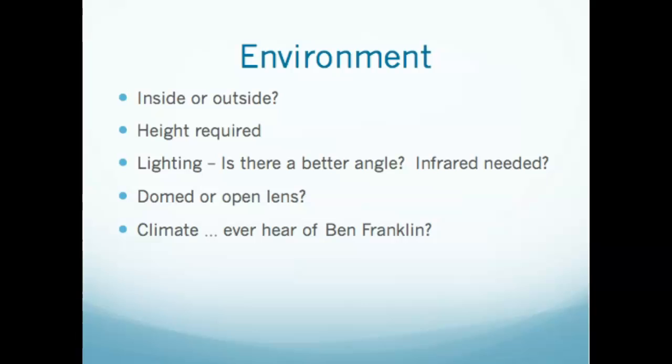Domed or open lens. So domed cameras, especially outside, are usually preferred, right, because they protect from the elements. But domed cameras, especially in cold environments, need a heater. And in very wet environments, they sometimes need to have a dehumidifier installed. And we saw some of those in last week's lecture, a dehumidifier, the small one inside of a camera. An open lens camera really doesn't have that problem.